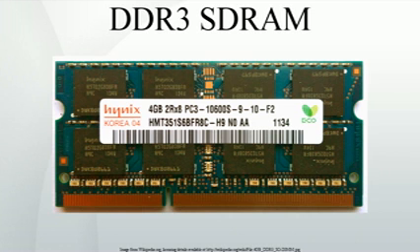DDR3 SDRAM is neither forward nor backward compatible with any earlier type of random access memory because of different signaling voltages, timings, and other factors. DDR3 is a DRAM interface specification. The actual DRAM arrays that store the data are similar to earlier types, with similar performance. The primary benefit of DDR3 SDRAM over its immediate predecessor, DDR2 SDRAM, is its ability to transfer data at twice the rate, 8 times the speed of its internal memory arrays, enabling higher bandwidth or peak data rates.